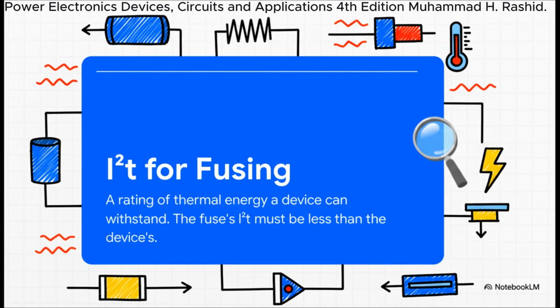But you can't just grab any old fuse. You have to be strategic. You need to look at a rating called I squared T. That's I²t. It basically represents the total amount of thermal energy a device can handle before it's destroyed. The rule is simple, but it's absolutely critical. The I²t rating of your fuse must be less than the I²t rating of your semiconductor. That way, when a fault happens, the fuse blows first, saving your much more expensive power transistor.